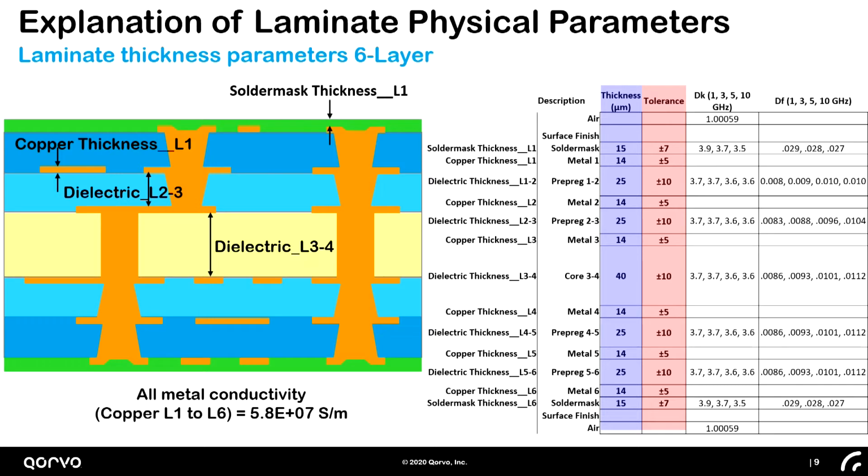The other thing besides the thickness variation is that the registration, the alignment between this layer and this layer, is really bad. It's like plus or minus 15 microns. I've seen people try to build couplers back in the days when it was plus or minus 25 microns and use a 25 micron line. I don't think that worked. It's like they weren't even on top of each other anymore. So that's the kind of thing that we're talking about here.